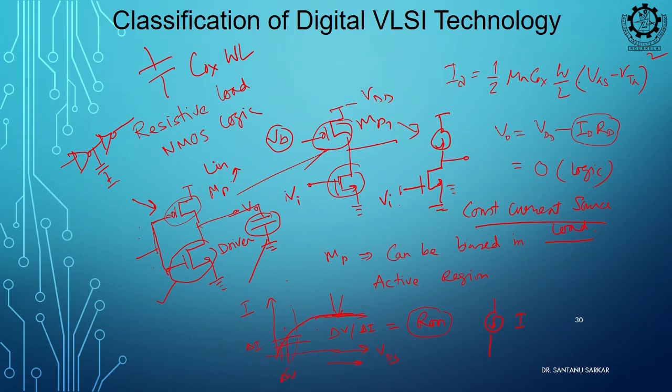Now, the difference is this output, this node is my output, right. This will be either 0 or 1. These two are the possibilities, right. Digital circuits have binary logic. Binary logic has two values only, 0 and 1. So, you see when it is 0, this cap is connected to the ground through which? Through this NMOS. So, it is strongly connected to the ground.